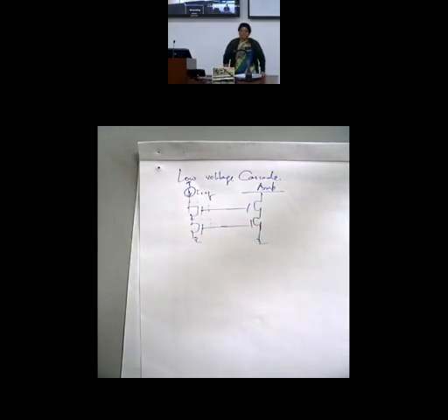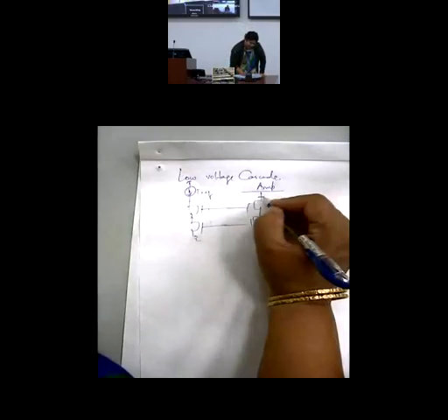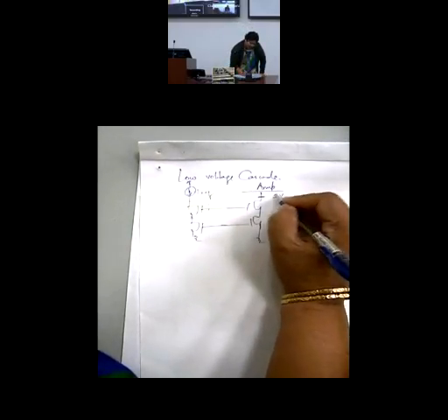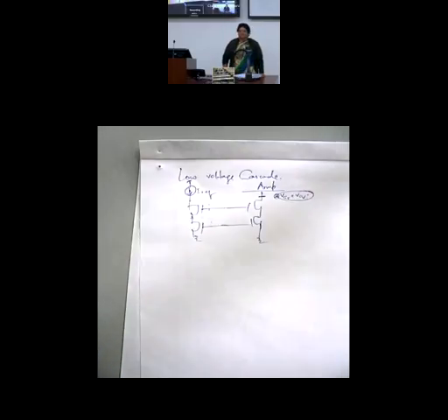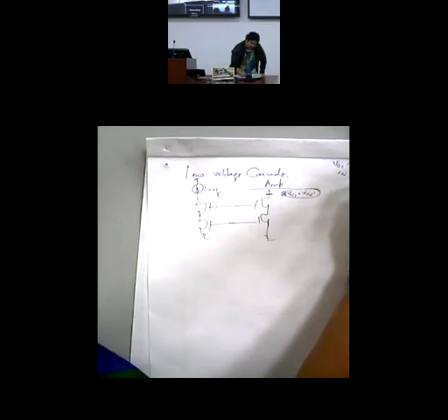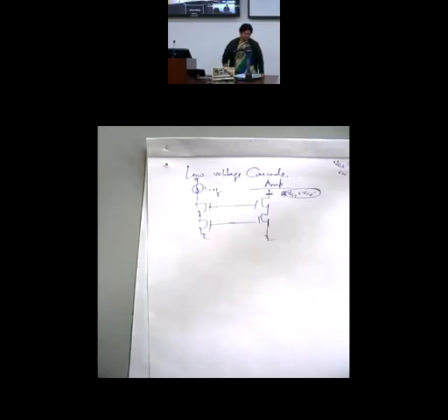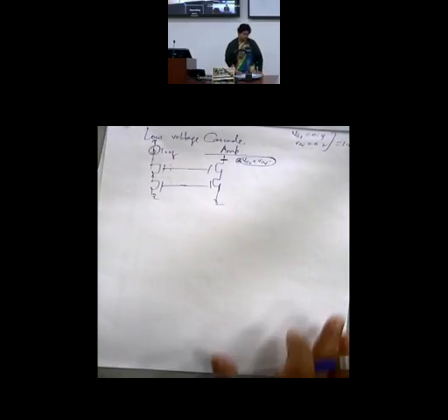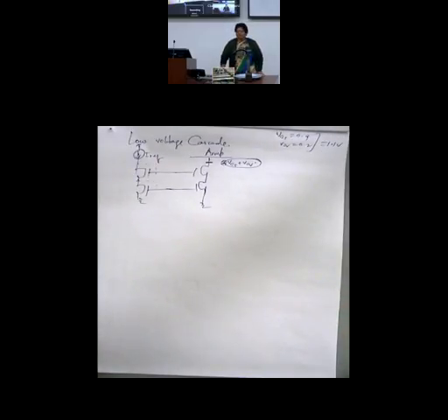But here we make a change, because I do not want this to be VGS plus V overdrive. Initial value for a cascode, which comes out to be for VGS to be 0.9, V overdrive to be 0.2. This gives me a loss of 1.1 volt, which I don't want.